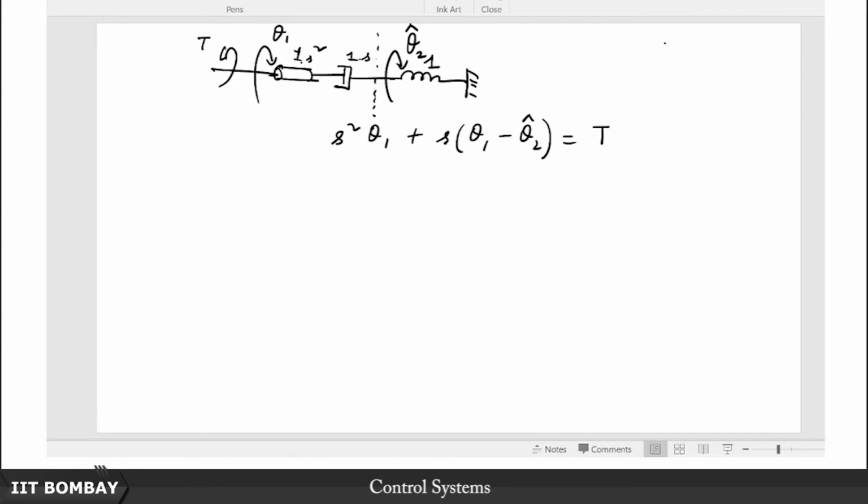So you will then see that this is like S, so this admittance is 1 by S, and this one has 1, so you have 1 by S times 1 by (1 by S plus 1), that is going to be the equivalent admittance. You can take that as an exercise, and you will come up with eventually the same result that we will get to using our equations here. What about the second case here?